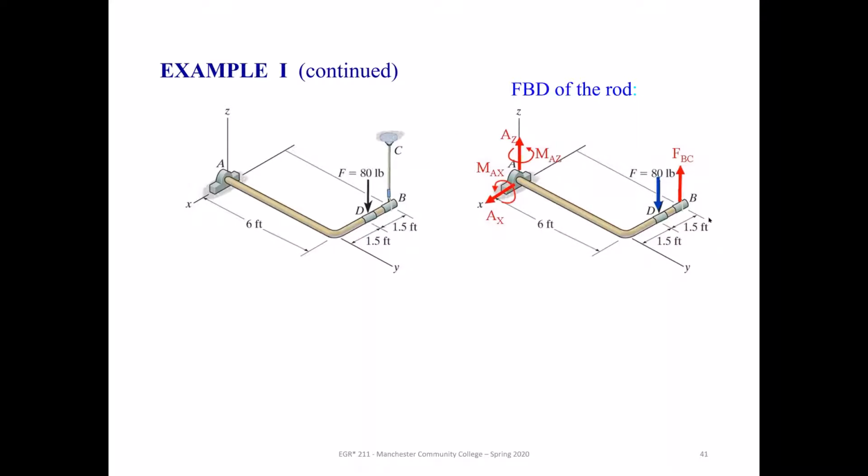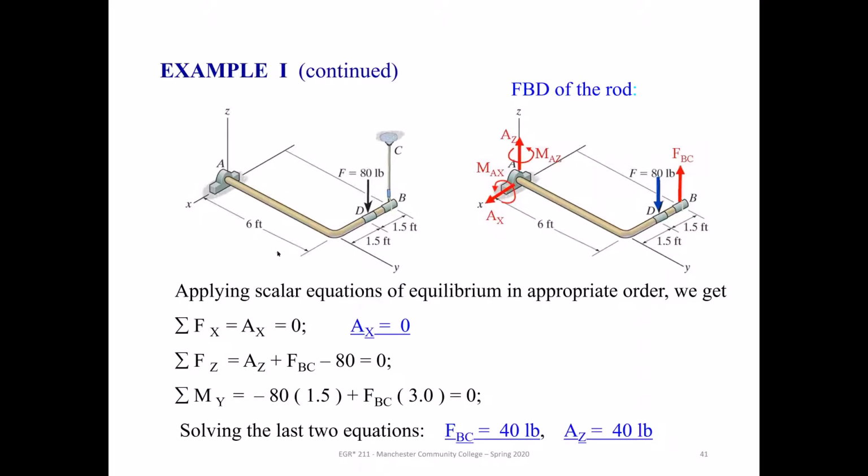These are all the forces that are involved in this problem. All the reactions, reactive moments, and forces that are involved in this problem. Okay, so our free body diagram is correct. Okay, so first part, you can sum all the forces, summing all the forces in the different directions to solve for those unknowns. Okay, so we need to find this AX and AZ.